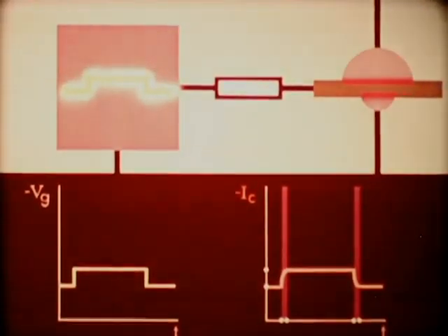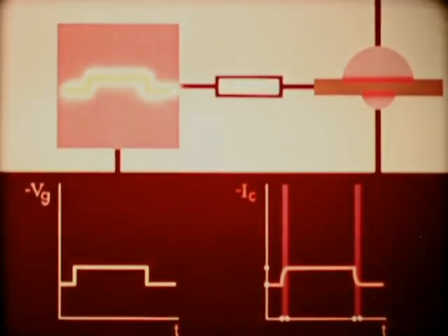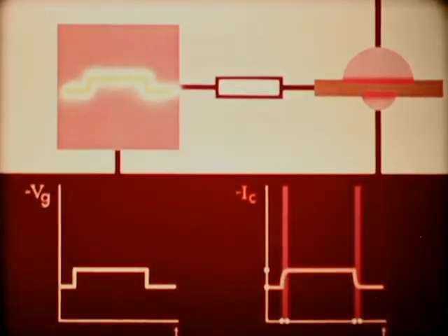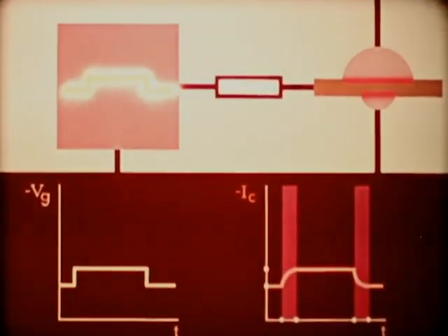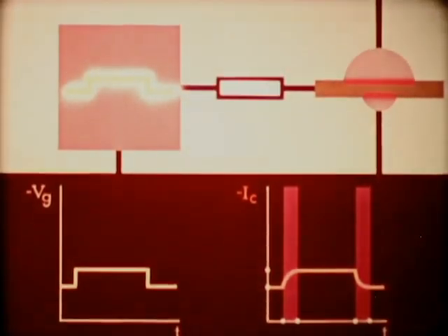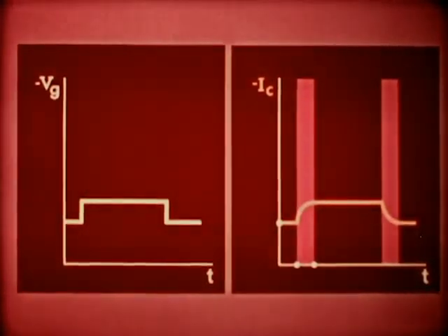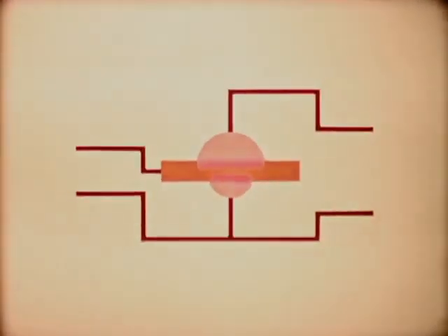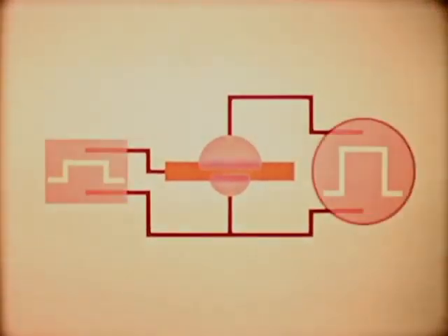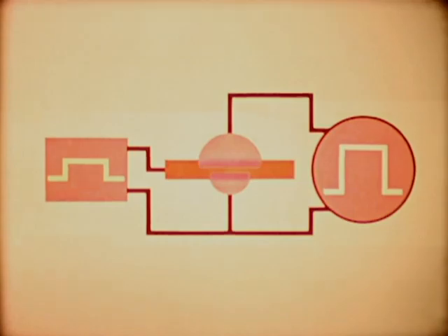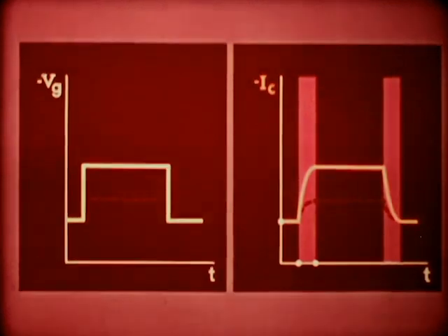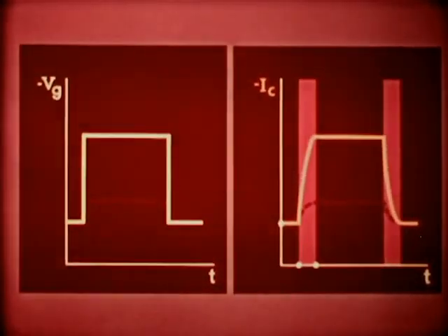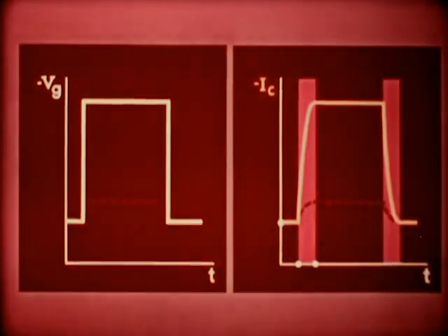Consequently, there will be a considerable increase in the times necessary to bring about a change in the concentration curves of holes and electrons in the base. Thus, TR and TF will also increase. Up to now, we have considered the time taken for small current variations to occur, which in fact means that the transistor is acting as a pulse amplifier. When a higher input voltage is applied, the output current also becomes higher, but the rise and fall times remain the same as before.